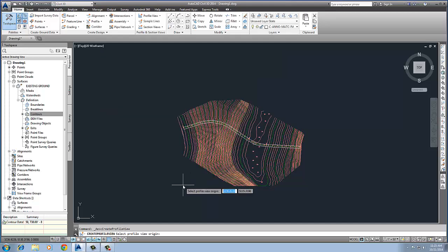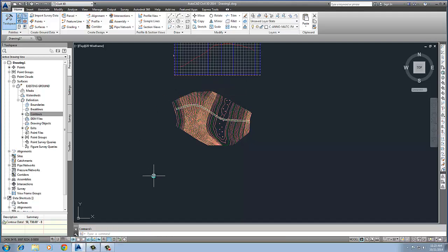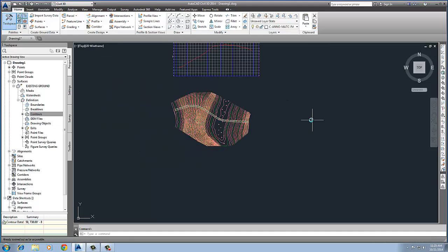Where you place the profile really isn't important. A lot of people in highway work, in particular, work in what's called a plan and profile sheet, and so usually your plan's on top, profile's on the bottom. I could put that here, I could put that here, because I'm going to be in paper space when I do that anyway, so it really doesn't matter. I like to work close to where the 0 line is, so I'm just going to click it above that a little bit. And you should notice your profile now came in.